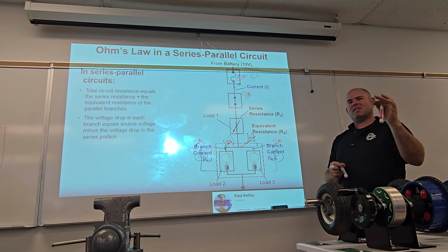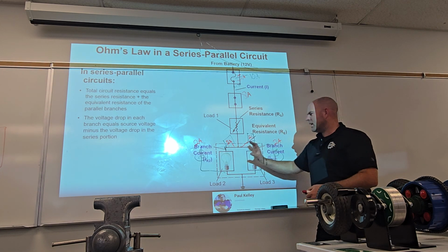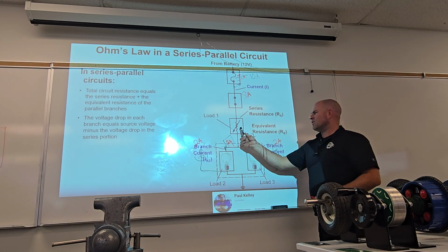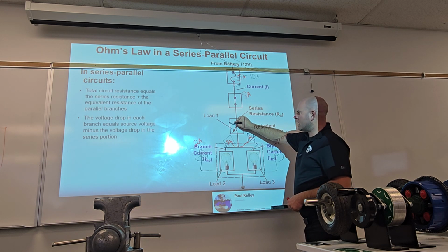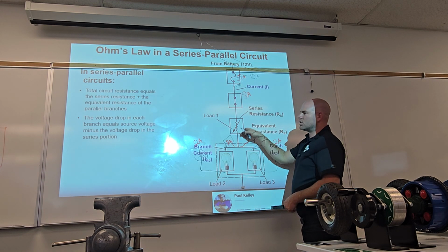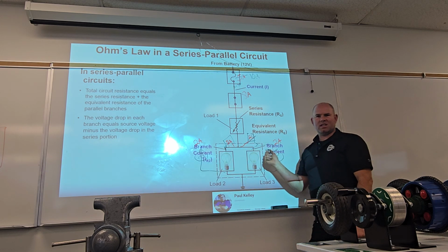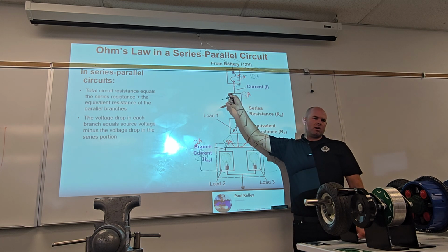Now, here's one crazy thing you could do if you're the truck driver. If you wanted to have 4 lights in your trailer because you want to look cool at the truck stop or whatever, if you were to put a load right here, you could actually increase the resistance right here, which would decrease the amperage in the series circuit, which would technically decrease the amperage right here. You'd have 4 bulbs in there, but they'd be 4 dim bulbs. And you could keep it under 8 amps.